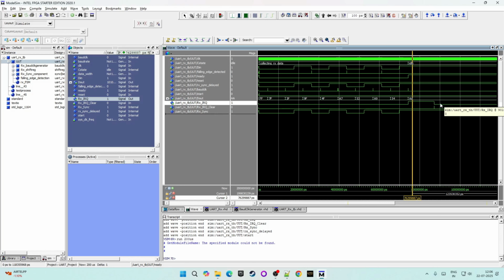And now I am satisfied with the results. You have seen that we have changed many things in multiple modules. We have adjusted our Baud clock generator to work with the transmitter module as well as the receiver module. We have fine-tuned our finite state machine to fix bugs that were unexpected, or that we had not even thought about. When we simulated them in terms of waveforms, we came to know multiple problems one by one. Then we dug down into which signal or trigger was causing those problems, and we fixed them one by one.